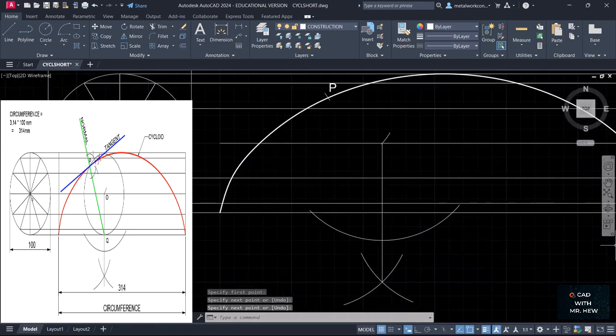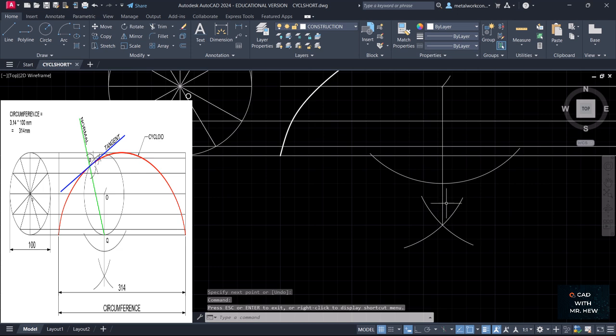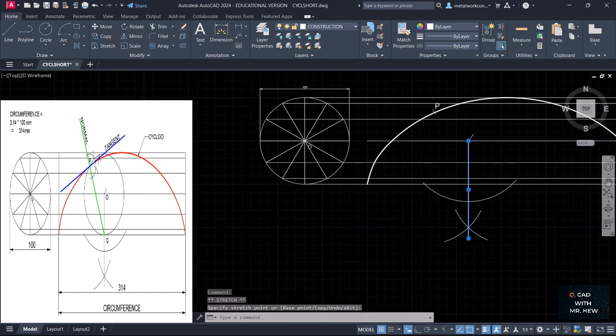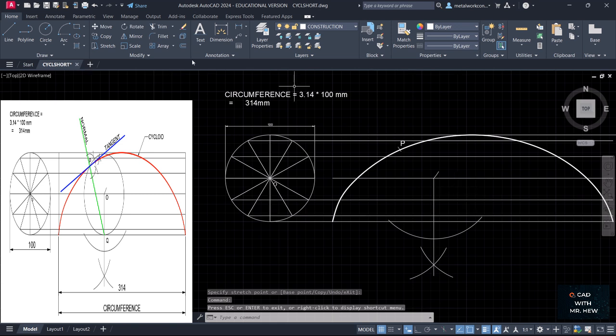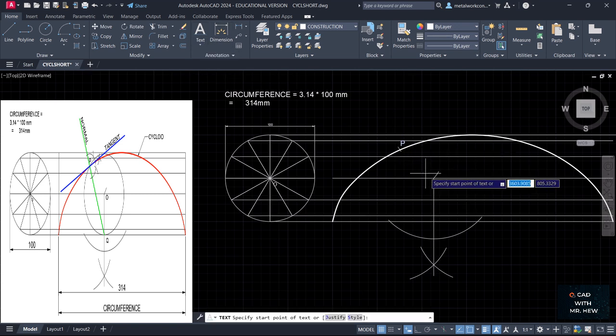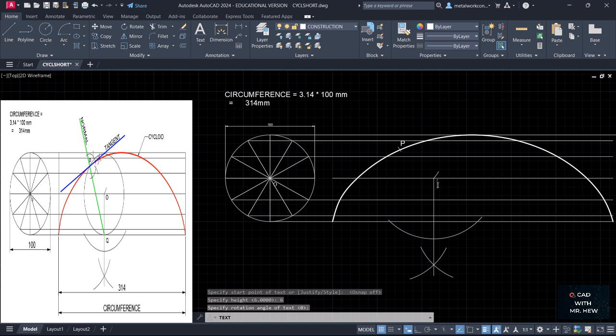In technical drawing, we normally extend the perpendicular beyond the intersection. All right, so that's a complete division. The next step now, we're going to draw a circle. So let me label this point O, single line text. I'm going to turn off object snap right here. This point will be O. So we leave 6 millimeter height, rotational angle 0. This point is O.